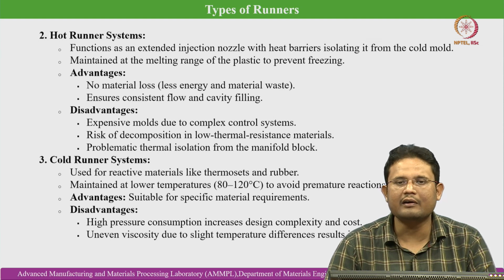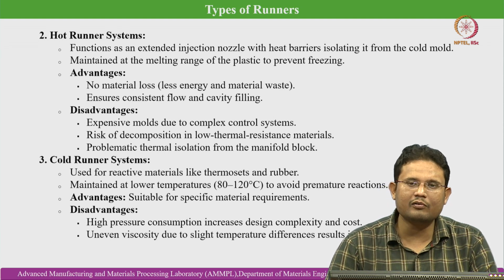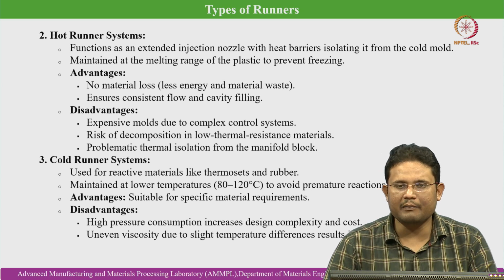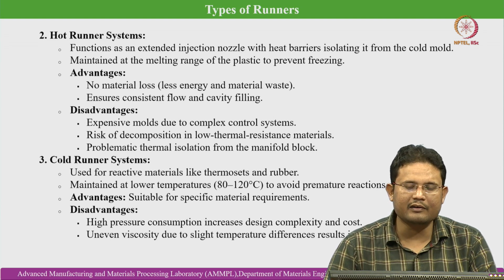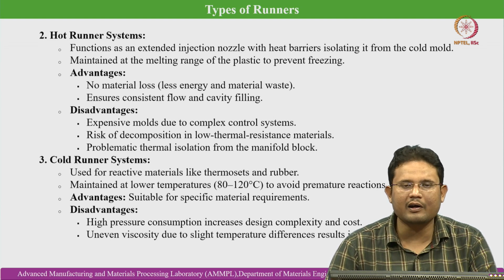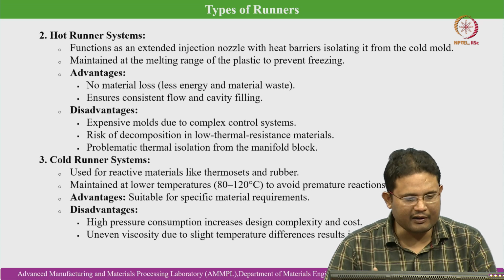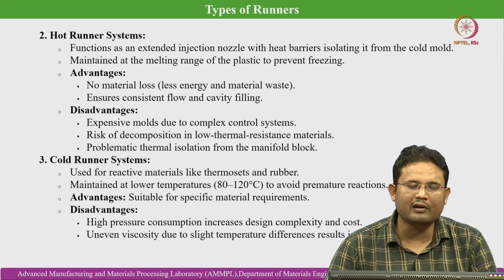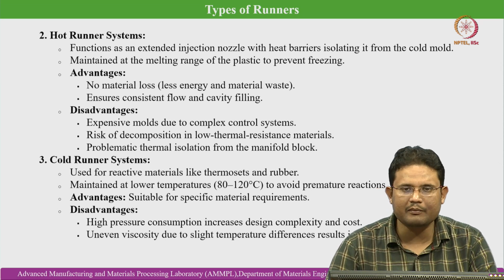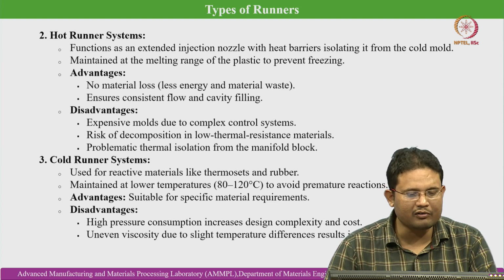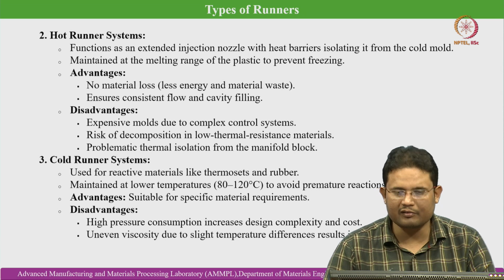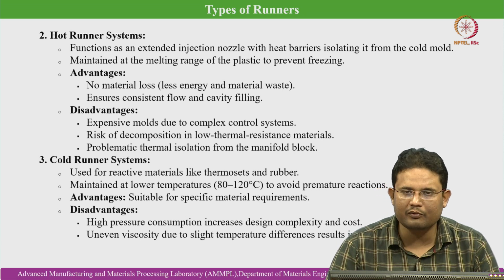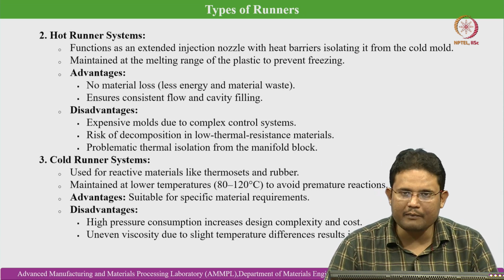So, you can understand that it significantly reduces waste generation, because the runner geometry always remains fluid and only the component cavity gets filled. However, it poses certain complexity in the design of the runner systems, and that is also a disadvantage, because it significantly increases the cost of the mold. There is also a risk of decomposition for low thermal resistant materials, because they are exposed to heat for a longer period of time.